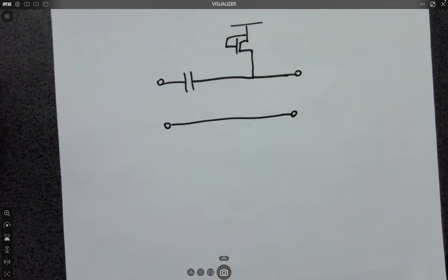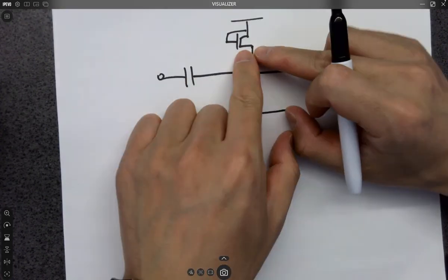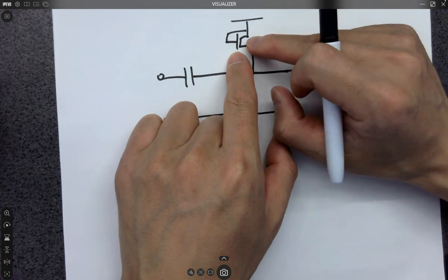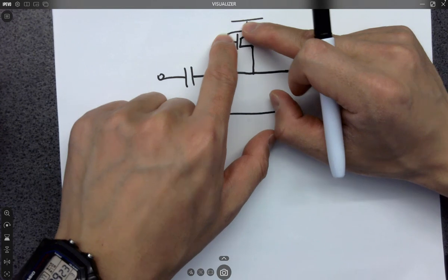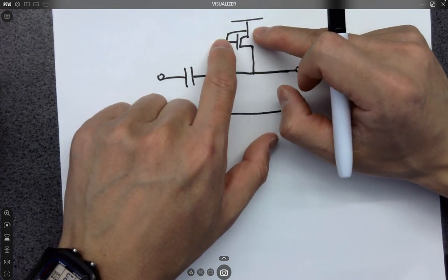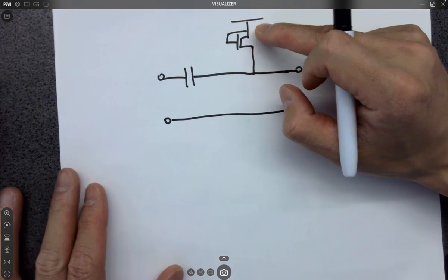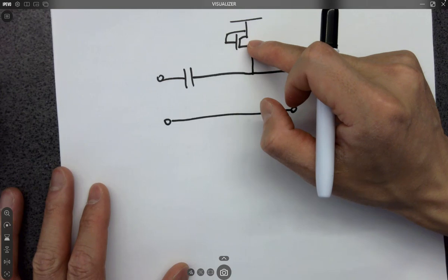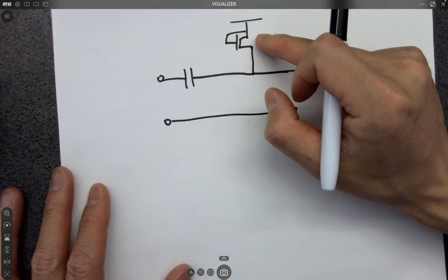And most transistors are way easier to fabricate than the diodes, right? Because most of the circuits are CMOS transistors, we can just add another CMOS transistor and make a gate-drain connection, then I can form a device which performs very similarly to the diode. So usually we use this kind of connection for a transistor as a diode in the circuit.